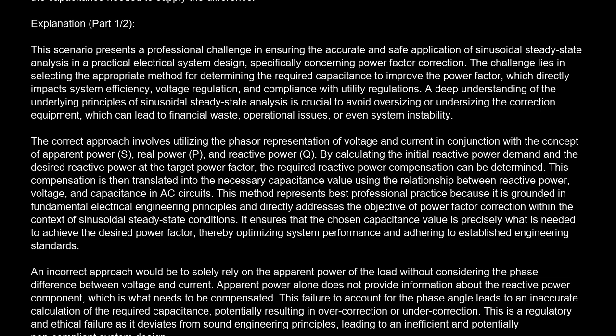The correct approach involves utilizing the phasor representation of voltage and current in conjunction with the concept of apparent power S, real power P, and reactive power Q. By calculating the initial reactive power demand and the desired reactive power at the target power factor, the required reactive power compensation can be determined. This compensation is then translated into the necessary capacitance value using the relationship between reactive power, voltage, and capacitance in AC circuits.